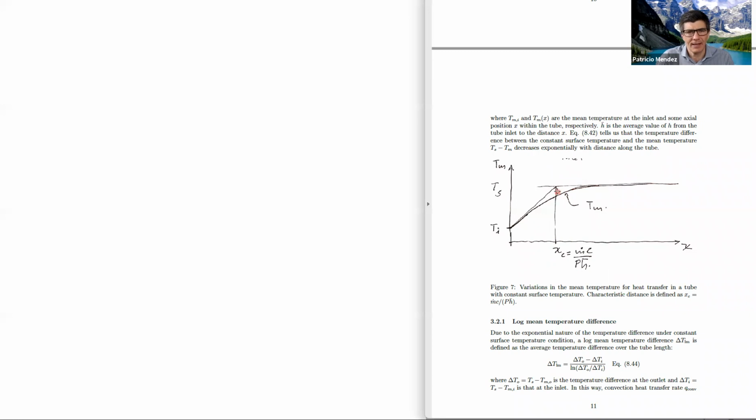If you go longer than that, your heat transfer is so little, but the price you pay for the pipe is the same price you pay for the pipe here that is transferring a lot. You're way better off having two short pipes than one long pipe. Now, having two short pipes sometimes means things are more expensive. You need to weld both ends, right? While one longer pipe can be cheaper. So there is a balance. For sure, you don't want to make it too long because you start losing money again.